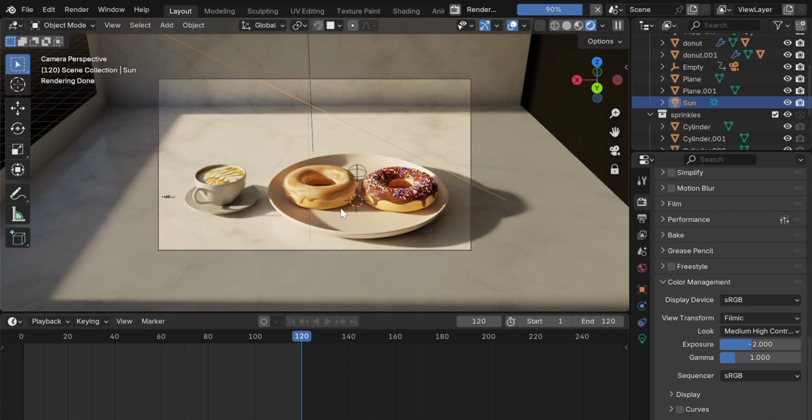Whenever possible, try to solve lighting problems using 3 lights or fewer. Instead of adding new lights immediately, focus on improving how the existing lights work together. Because once too many lights enter the scene, surfaces start to flatten. Materials lose depth, shadows lose meaning. Instead of realistic surfaces, you end up with something artificial. Lighting determines how every object appears. If lighting is incorrect, shape and material both suffer. Details disappear. So treat lighting carefully.